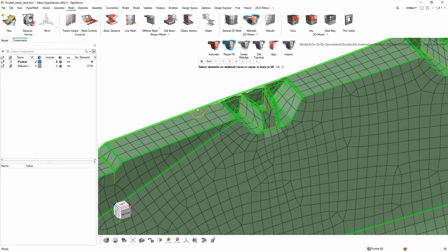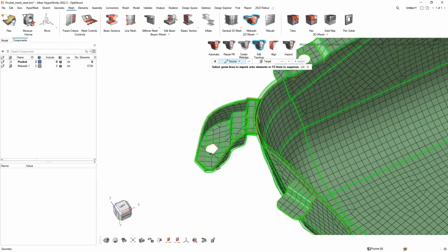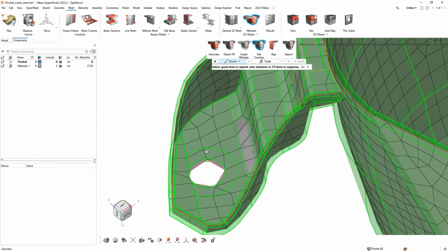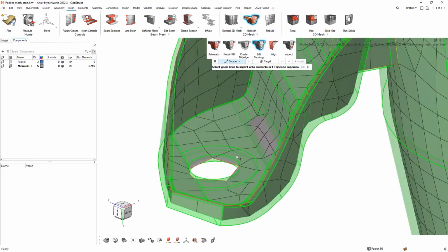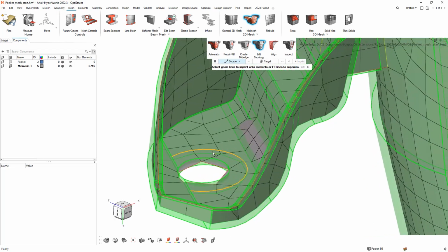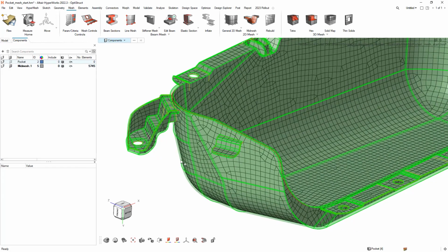This back edge will repair in a second with the inspect tool, but I wanted to show the ability to edit the topology. When it generates the mid-mesh, it will automatically ignore certain flat features to try and improve the flow of the mesh. But we have the option as a user to give it a dedicated imprint. So I can pick this washer imprint and ask it to pass that edge down into the FE geometry. So again, complete control over the resultant topology if we need it.